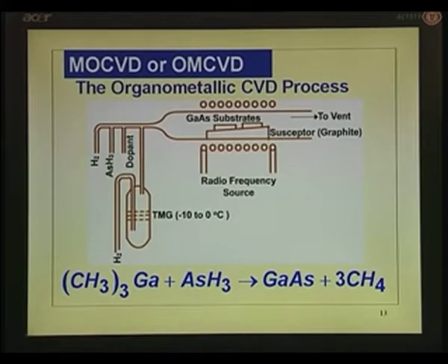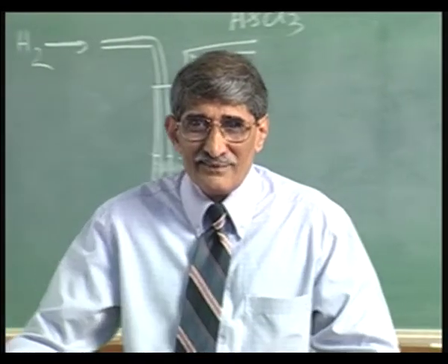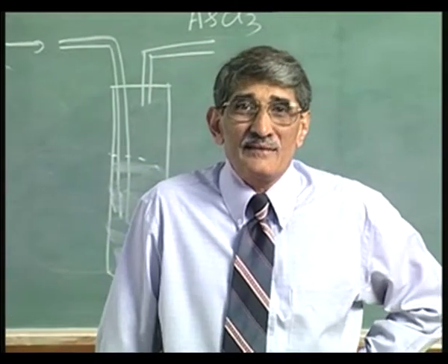So, the merit of this metal organic CVD is you can get binary compounds like gallium arsenide, you can get ternary compounds like aluminum gallium arsenide, gallium indium arsenide. You can also dope them with zinc, using diethyl zinc or trimethyl zinc. Okay. And of course, you can add dopants like sulfur, use another bubbler, that means you will have all bubblers hanging around, connected to the system reactor.